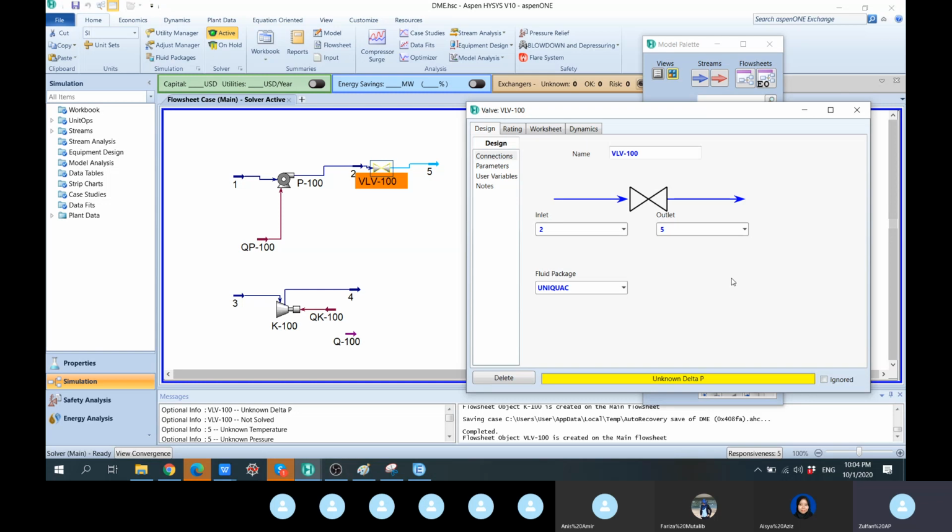Sorry, how many equations do we have? Only one: flow rate equals CV times the square root of delta P, typically divided by the specific gravity.